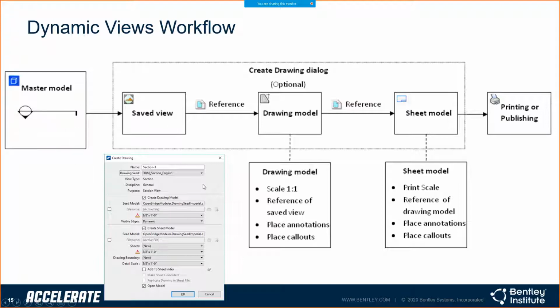All right. So we have a create drawing tool, and this looks very similar whether you use, let's say, the section callout tool or the elevation callout or some of the different ones. This particular one is from the section callout, and that's the one I'm going to probably use the most today and refer to the most, but just so you know, there are others. In this tool, when you call it up, initially you have to give it a name up here. What this name is doing, this part of the dialog, is basically just creating a saved view.